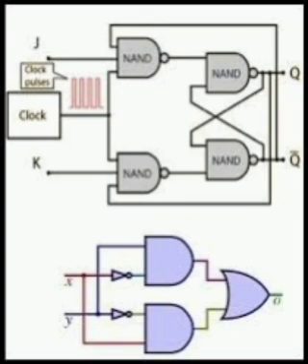Using 1 2 power n is to 1 mux, all n variable logic functions can be implemented. Some n plus 1 variable logical functions can be implemented. Using 1 2 power n is to 1 mux and 1 NOT gate, all n plus 1 variable logical functions can be implemented. Demultiplexer. It receives information on a single line and transmits it on one of 2 power n